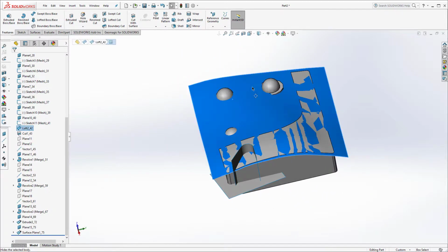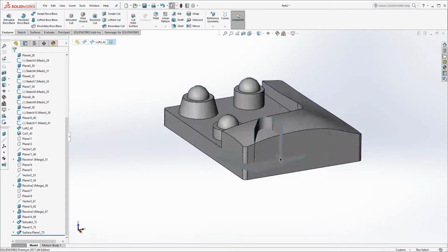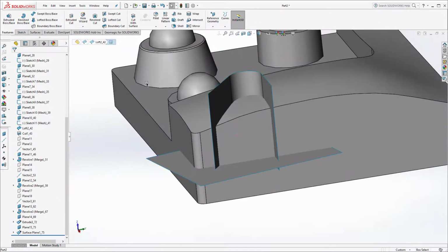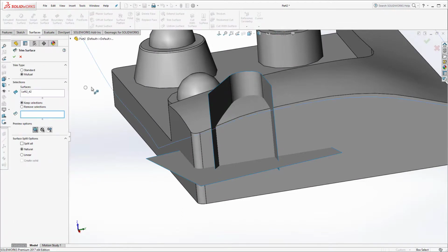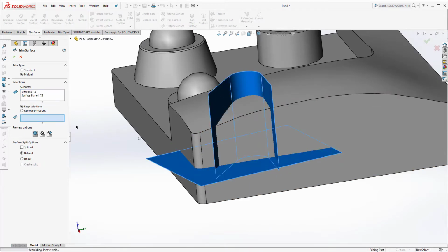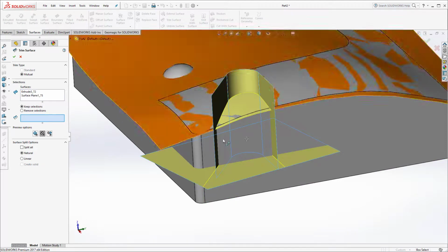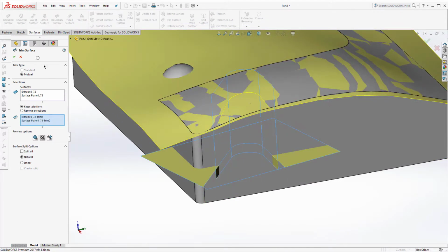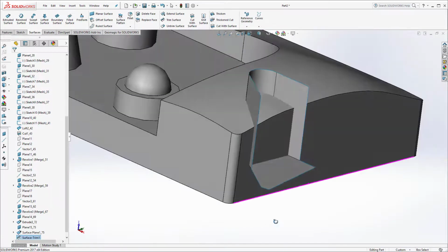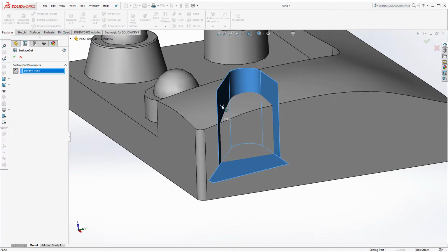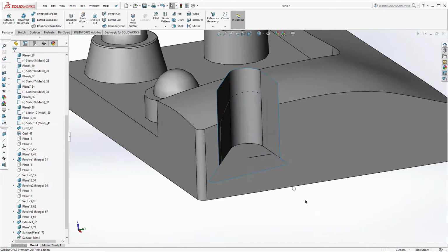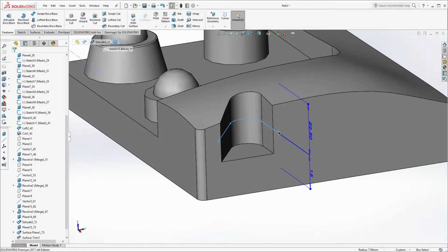And then in SolidWorks, especially if you are using this live transfer tool, you're most likely a SolidWorks user, and you're going to be very familiar with how they do things over here. So you can model things in a certain way to where you would avoid having any sort of issues like this. But I like to show how the interface works because it's a very simple process to come in and say, I'm going to trim these myself together. And then I can do my own cut with surface right here. And you'll see how their interface does cut with surface a little bit different. And then when I'm done with that, I can turn it off.